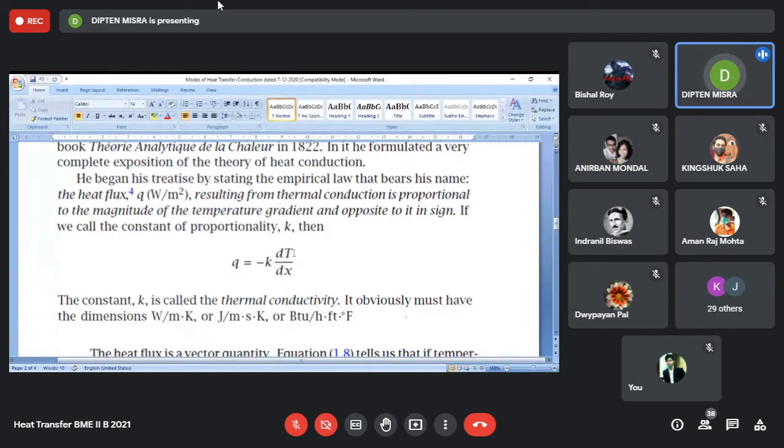The temperature difference will be the same whether the temperatures are individually taken in Kelvin or degree centigrade. So here this K represents the temperature difference in Kelvin, and temperature difference in Kelvin and in degree centigrade will be the same. If there is a temperature difference of 2 degrees centigrade, then Kelvin wise it will also be a temperature difference of 2 Kelvin. So the unit of conductivity will not change whether we take it in watt per meter Kelvin or watt per meter degree centigrade.